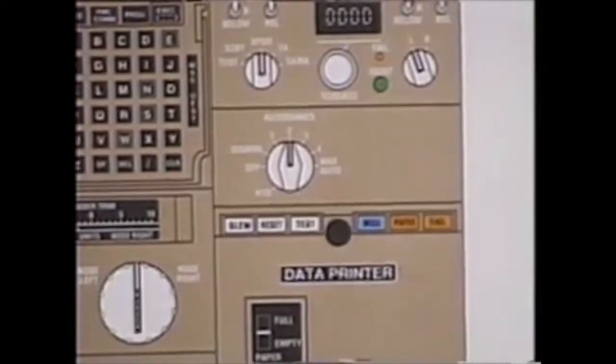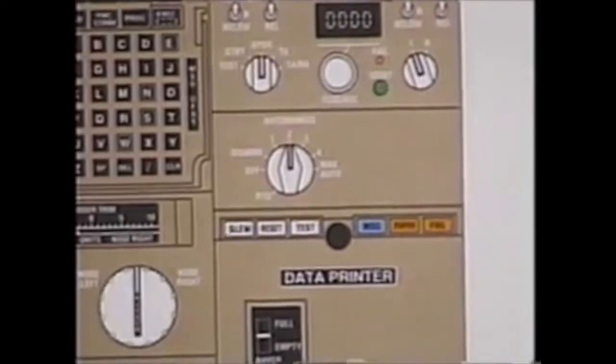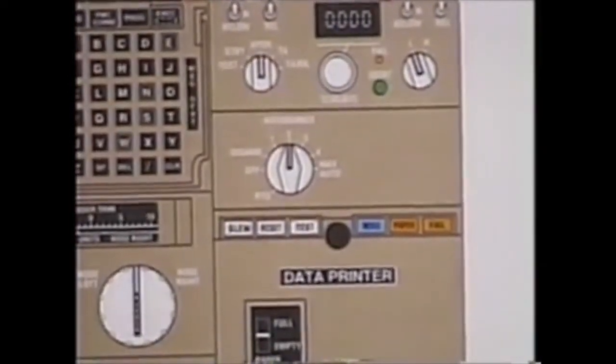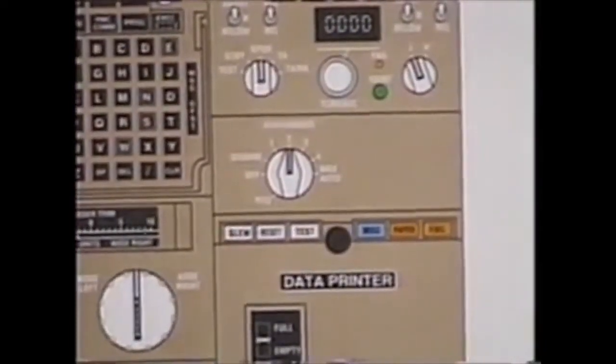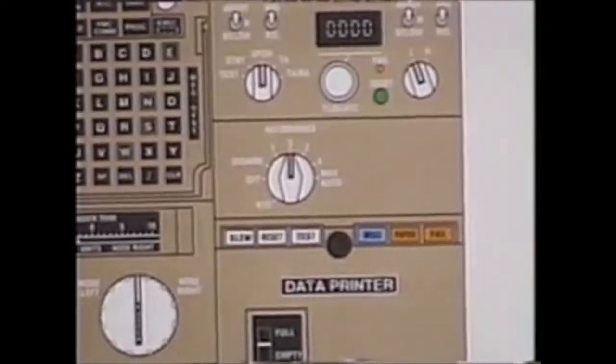You will get max braking to a complete stop if you do not disarm RTO. RTO will not factor in reverse thrust. RTO does not compute an acceleration rate. It allows max braking to occur to a complete stop. You cannot physically outbrake RTO.